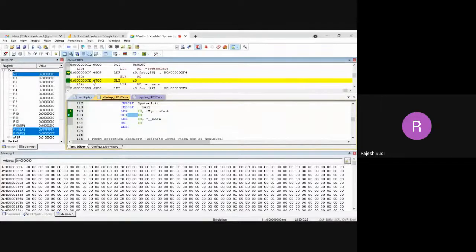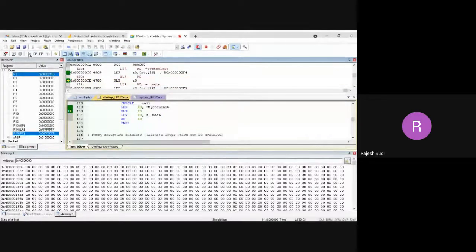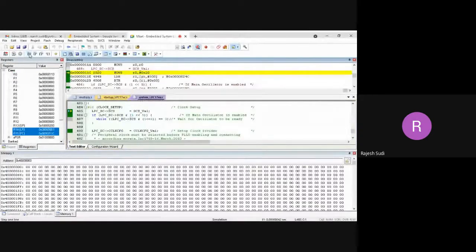In the disassembly, you can see the program counter value is CC. So then now it is BLX R0, small R0. It is going to that. Okay, so CE, it should be 105. If it is 105, then it will come back. Otherwise, since 11D is loaded, CE. See here, 11C is loaded, so therefore it is going to 11C in the disassembly.